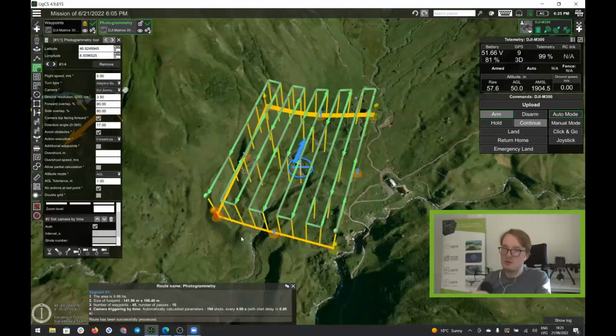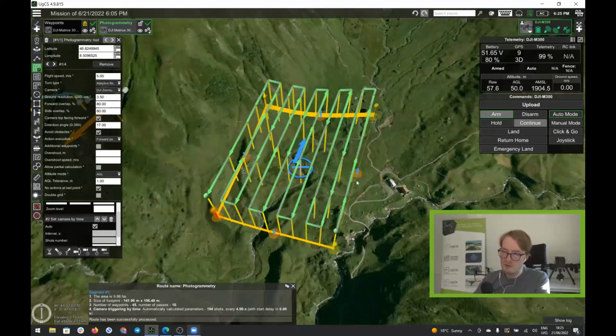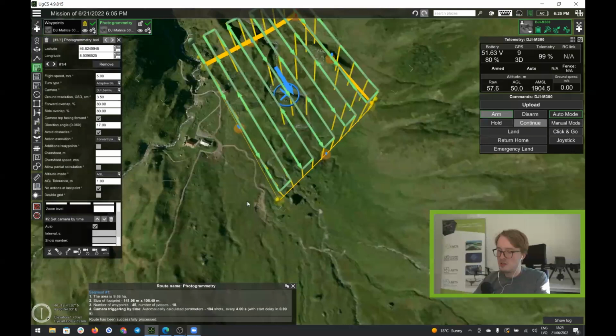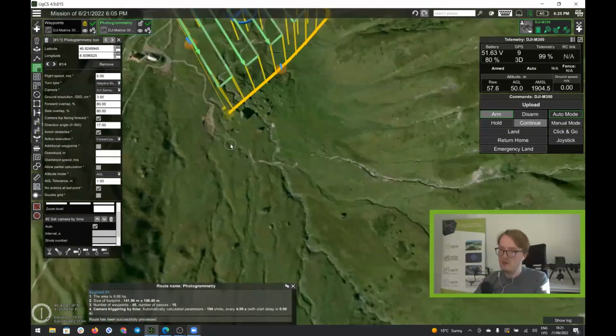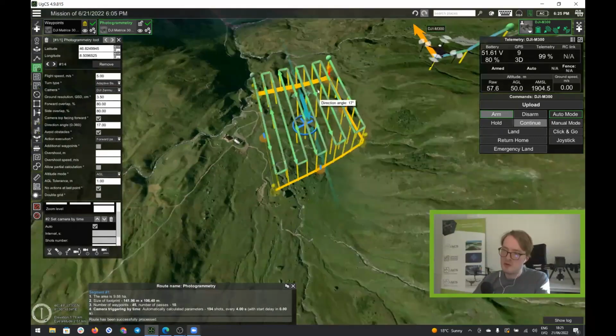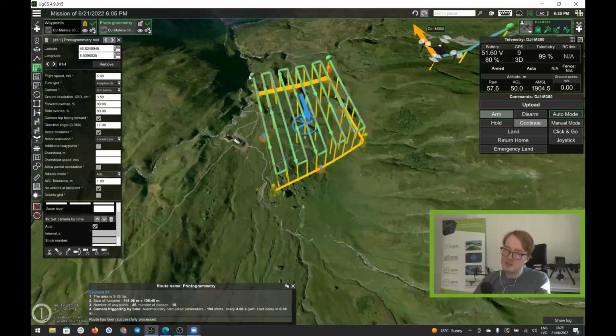And that's why for DJI drones, even though you can see here we have the takeoff and the landing actions, I'm not really using them. And also, I do prefer to have a waypoint before the photogrammetry flight, but again, it's not mandatory. You can simply have a photogrammetry flight like this and then fly it. But in this case, let's say you have constructed that flight and you are, for example, located somewhere in here. This means that once you send the drone on the mission, first it will fly to the furthest corner and then it will start the flight from here. And you can see it will end the flight in one of the furthest corners.